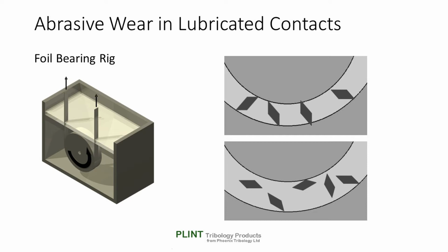This mechanism, perhaps similar in nature to conventional polishing wear, has been termed tumbling wear. With polishing wear, we would expect the free particles to roll through the tribo contact in continuous contact with both sides. The term tumbling is used to describe the situation in which particles are not in continuous contact with both surfaces, but are free to tumble through the bearing gap.